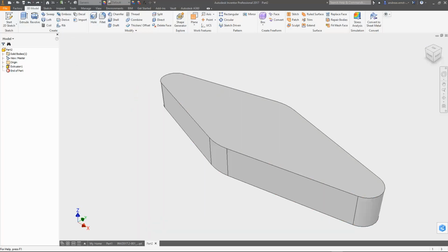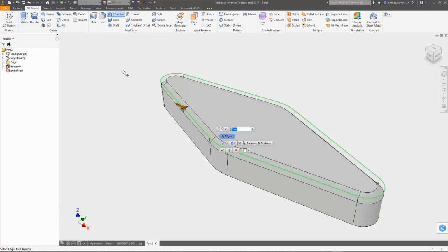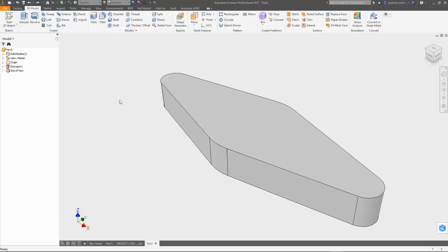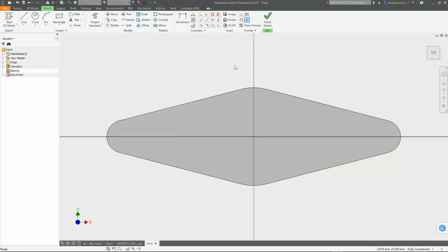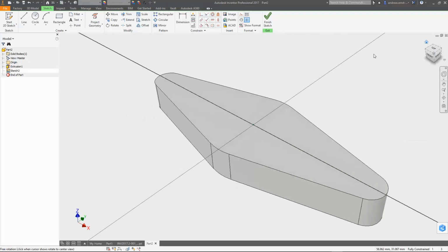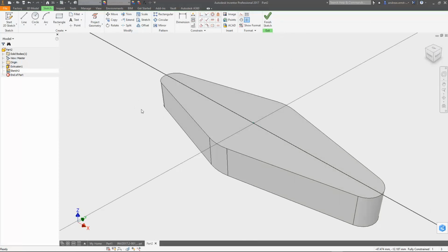Another use case for Select Tangencies is to select all tangent lines and to apply a fillet or chamfer. From my point of view, it saves a couple of single clicks per edge. As mentioned, as of Inventor 2017.3, you have the Select Tangencies command also available during the active Project Geometry command. The workflow to select faces and edges is identical.